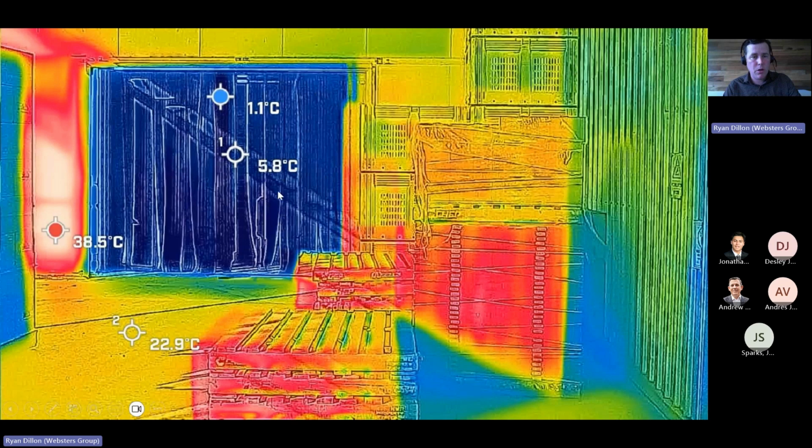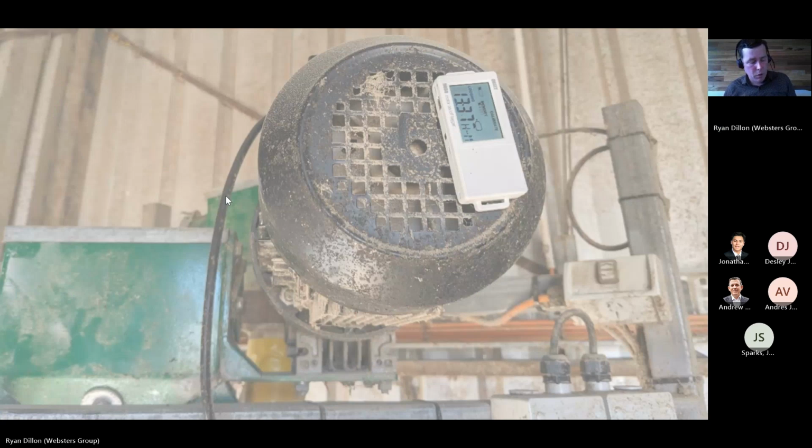So some ways to address that are to install plastic strips, as you can see here. These strips do have a few holes in them, so it's not a complete barrier as such, but it is helpful. So maintaining the strips is key, but also considering the amount of time the door's open is super important. So to put a number to that, quite commonly when we do a type 2 audit, data is so valuable, and the estimate of door openings is quite difficult to determine. Quite often you go to site and you ask the question, how often is the door left open? And you might come up with a certain number of openings, a certain number of minutes per day. The best way is to actually measure it.